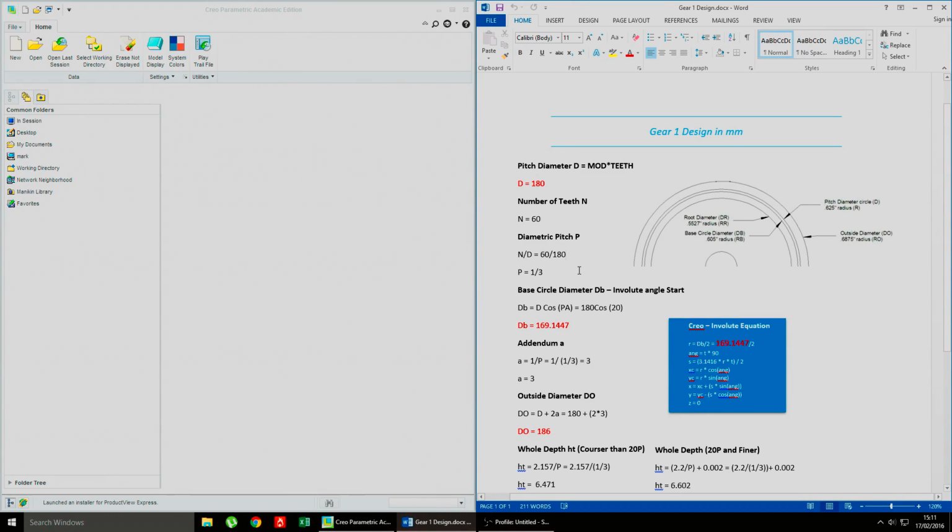to work. But there's 4 main diameters that you're going to be needing, and there's a little picture on it here. You need the root diameter, base circle diameter, outside diameter, pitch diameter as well. Now, when you're actually making your gear or choosing your gear, you'll know the pitch diameter. You might know the outside diameter, but let's say you know the pitch diameter. You can work that out by the module times the teeth number.